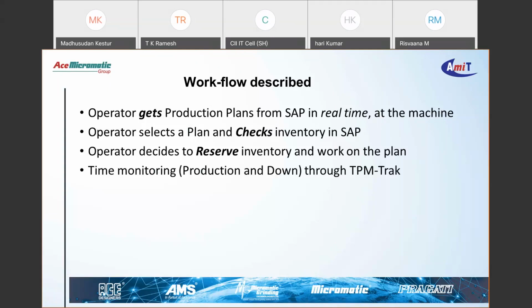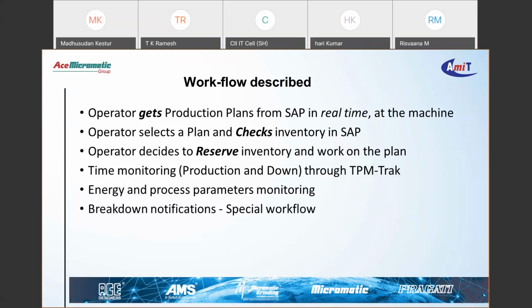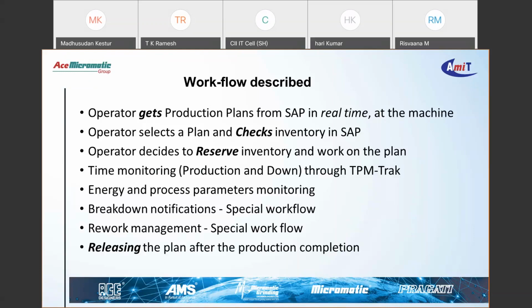During production, we monitor production time, downtime, cycle time, load and load time, reasons, rejection, etc. And we give OEE of the system in real time. We also monitor a lot of process parameters and energy. There are special workflows in place for notifying breakdowns and rework management. And then there is a concept of releasing the plan at the end of the